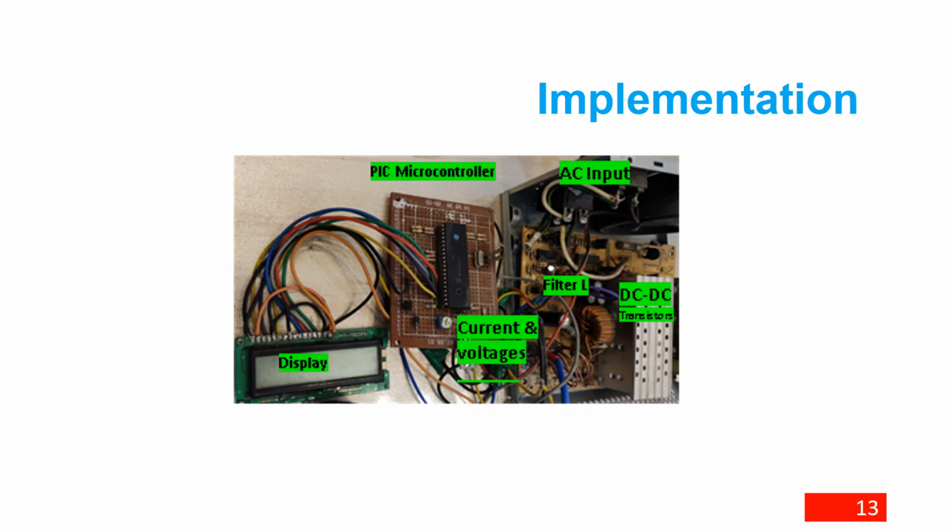The converter has been implemented physically. The prototype is shown. The converter is controlled through a 16F877A PIC microcontroller. The AC supply is about 250 volts, 50 Hz. The first stage of the AC to DC converter was energized to produce a rectified DC voltage for the second stage converter. The switch mode power supply is operated at 31 kHz.